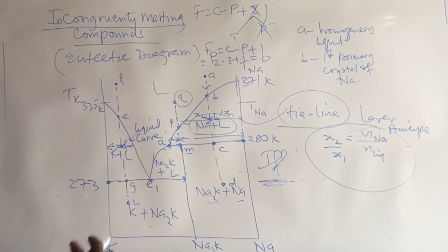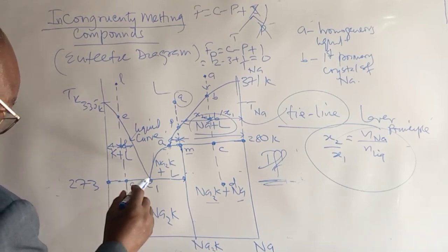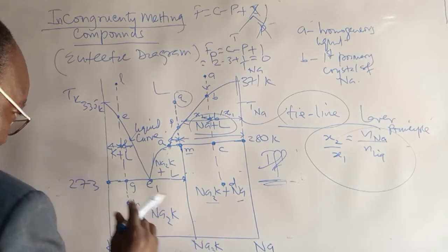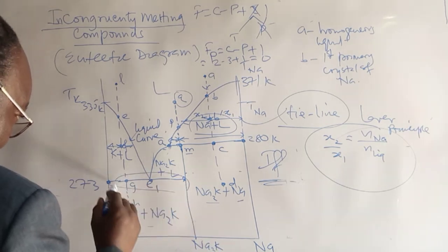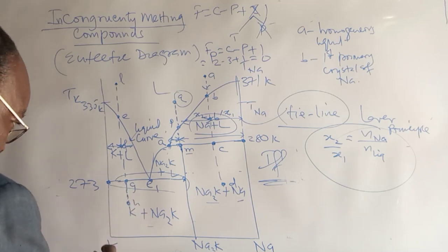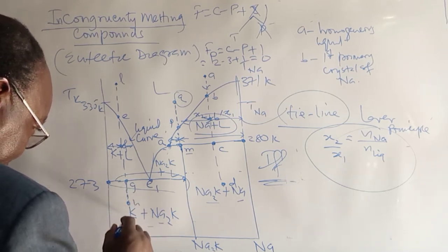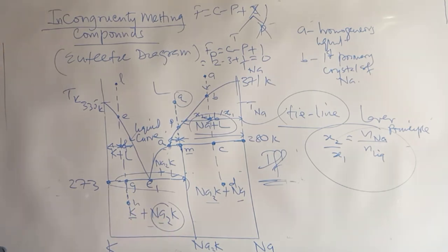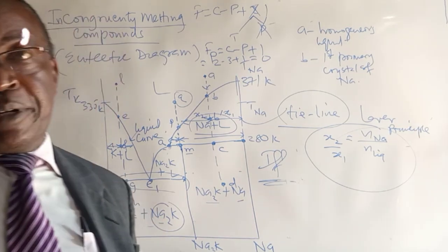Again, the system was invariant. Here also we now have this coexisting together with the eutectic mixture and the compound. So again, the temperature is constant. Then of course now when we start cooling down, the temperature is lowered. We are now forming this potassium and the compound. So basically we're just cooling potassium and the compounds. Very important for us to note.